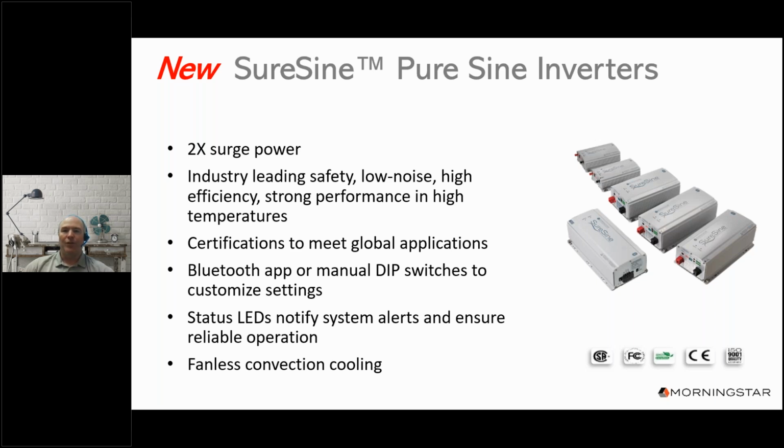And lastly, all the SureSines have a passive thermal heatsink to dissipate heat without the use of fans. Fans are a parasitic load, and they draw in dust and debris, and they are another component that's subject to failure. So all of these inverters are fanless.